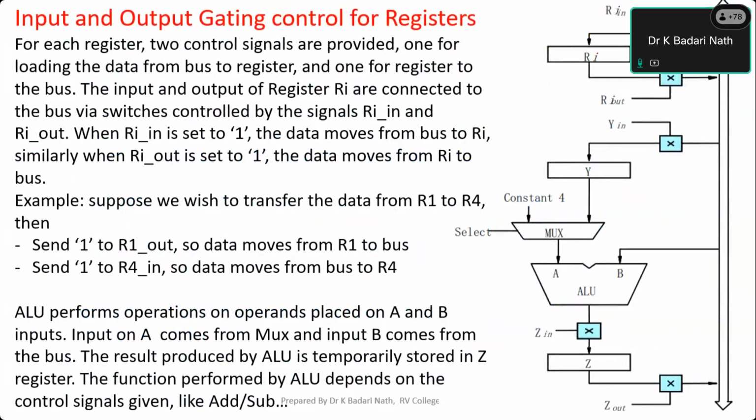What does it mean? It is like an inverter, but it will not invert. Normal ICs like an inverter, whatever logic 1 and 0 you give, you get some output. Whereas these tri-state buffers have 3 states. When it is enabled through the control line, whatever data you give it will pass to the output. Whenever it is not enabled, then whatever input is given will not be connected to the output. It will be open.